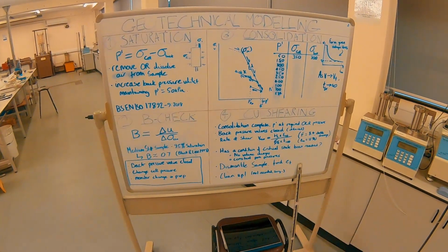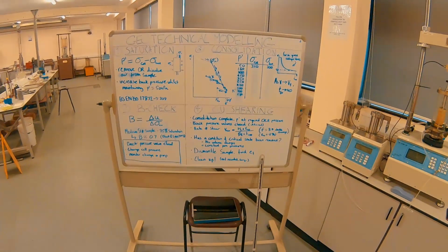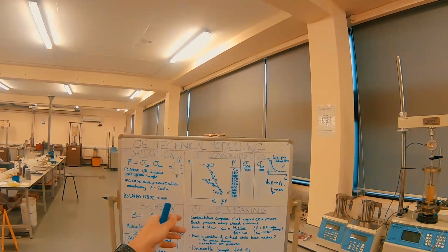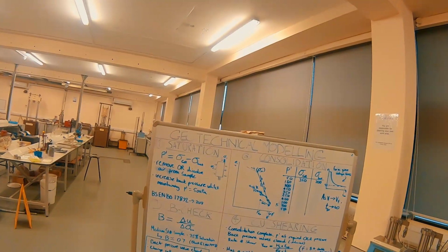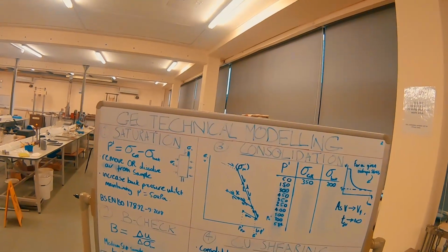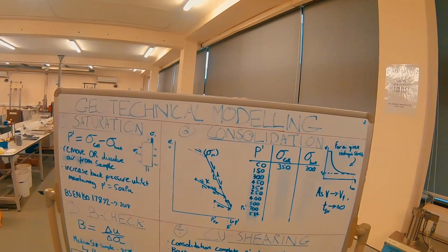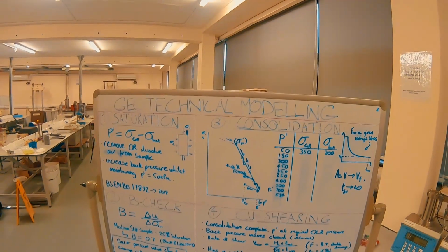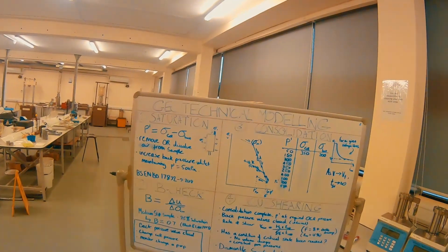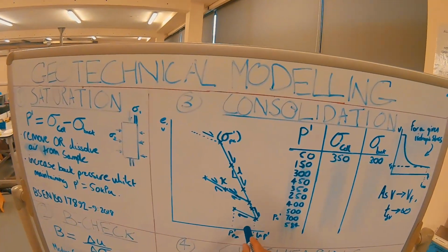And at 700 kilopascals, certainly for a sample that was only ever compressed up to 50 kilopascals of pre-consolidation stress, you hope that by that point you've completely destroyed the one-dimensionality and you know for sure that you're in QP space. That's crucial when you come to the shearing.